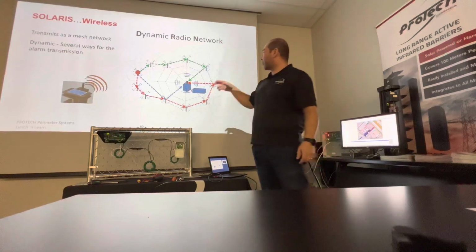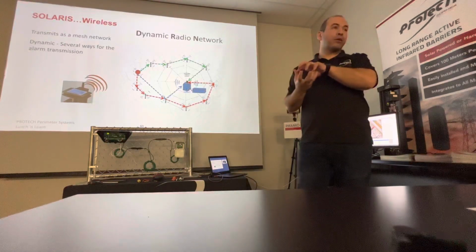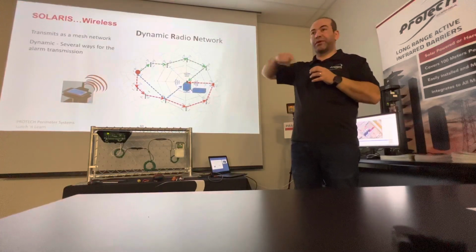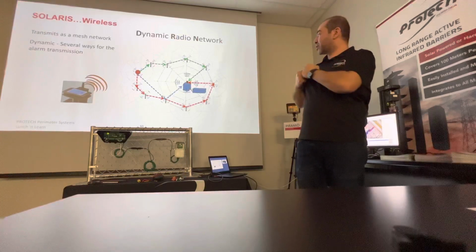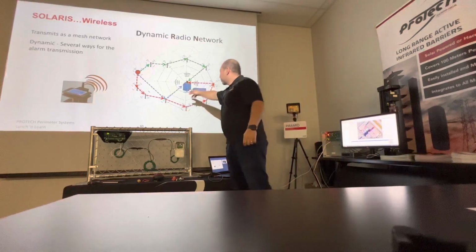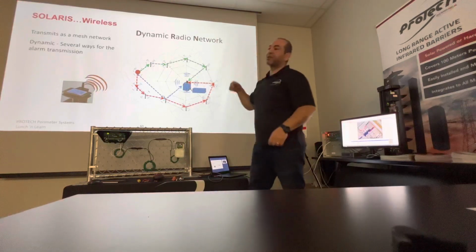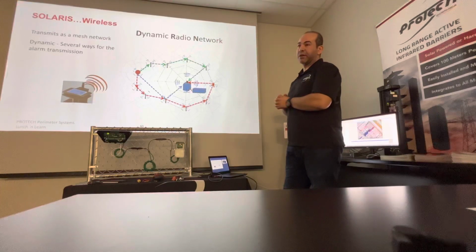And then it comes with a radio coordinator. So the radio coordinator is a small box that must be outside the building and needs to communicate with the nearest transmitter receiver. It grabs all the radio information, and then we have here our RS-485 communication to our Maximus. So this is how the information goes decentralized into the hub.